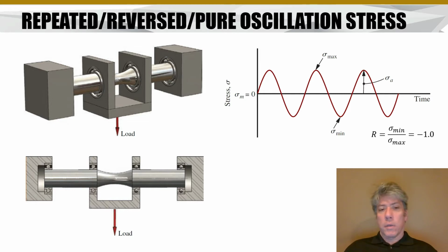And then all you really do is you just make that shaft rotate. Usually you'd actually have a motor on one side driving it, but the point is you turn this shaft with that load applied and measure the number of turns you get out of it until the shaft breaks, and it'll break in the center there.